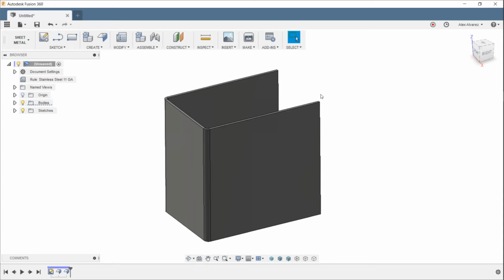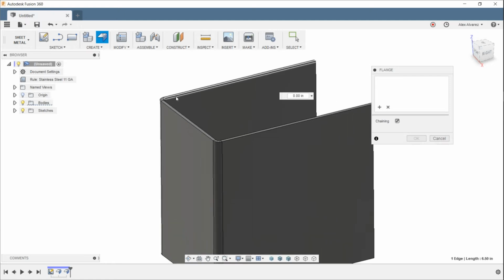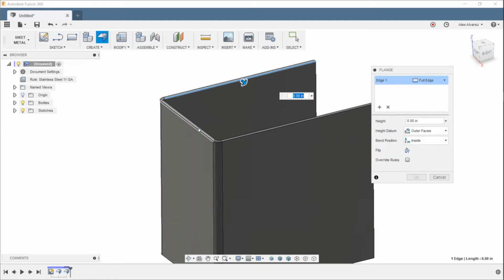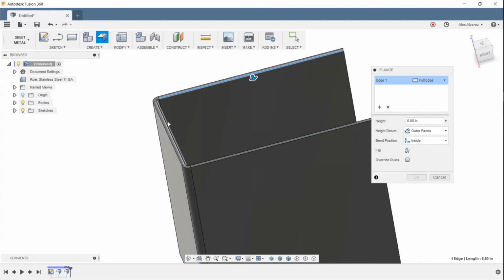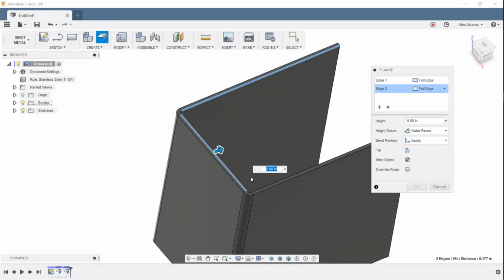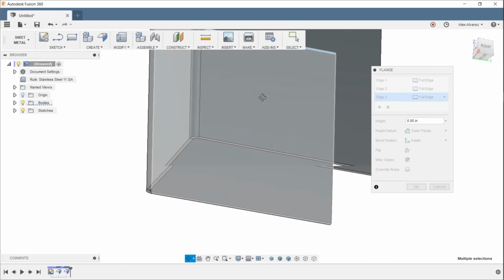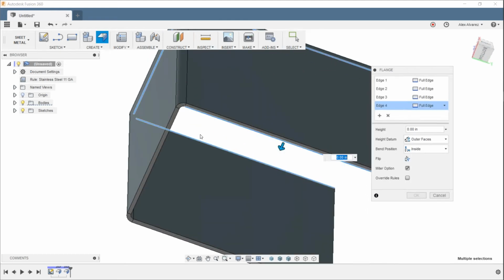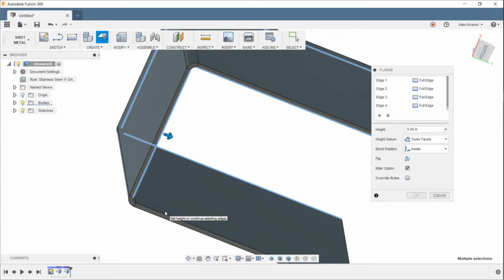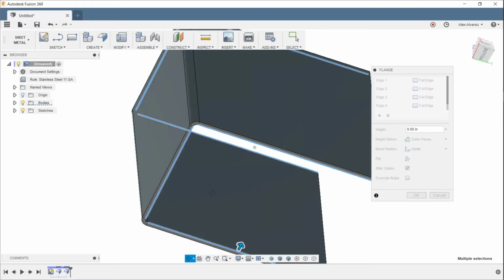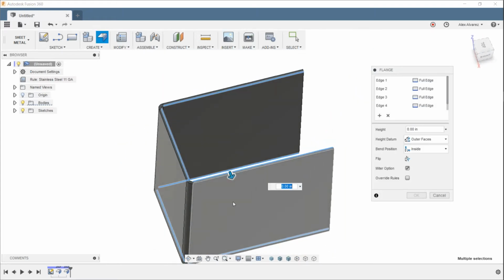And let's go ahead and create now the top, right? So the top and bottom flanges here. Again, I don't want to go all the way to the top. I can just right-click, repeat flange, and start selecting the edges that I'm going to select, right? So again, if you click on a wrong edge, you can Control and then unselect. So I want to go ahead and select these inner edges, these last three here. There we go. And then drag them towards the inside, right?